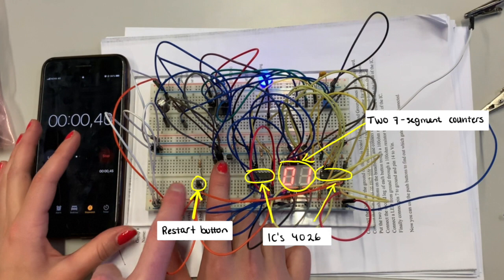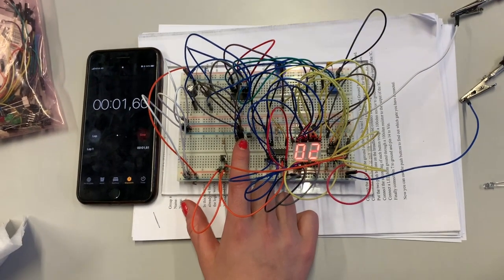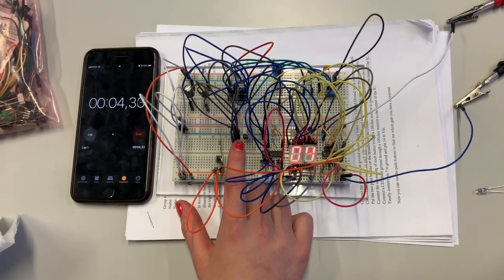The first 4026 IC will be connected to the second one from pin 5 to pin 1, but pin 5 is the carryover output pin of the IC and produces a pulse after counting to 9. The pulse goes to the clock on the second IC. This carryout only happens if the 4026 IC is connected to another 4026 IC. To be able to start a new heart rate recording without turning off the device, we also added a single push button which we connected to the restart pins on both ICs, so the count would start again at 0, and now the PPG is ready for the experiment.